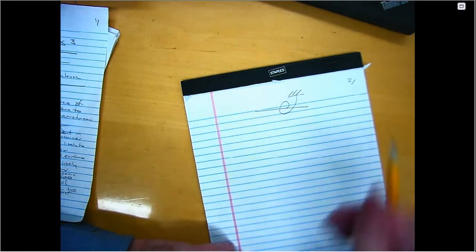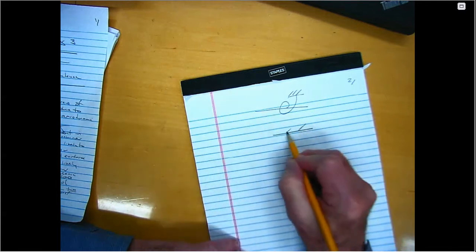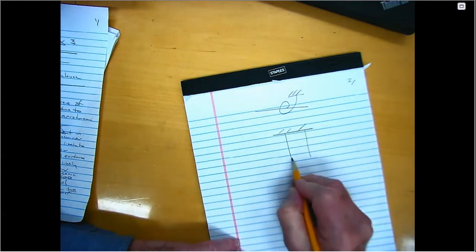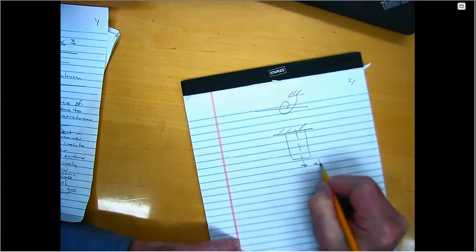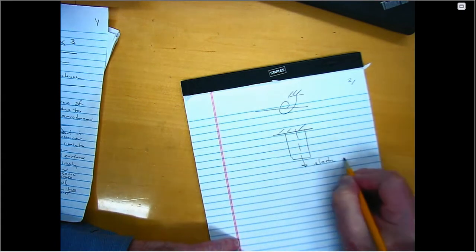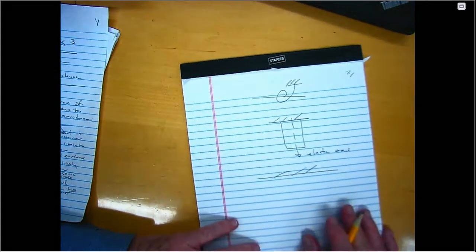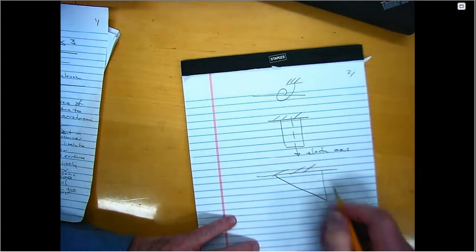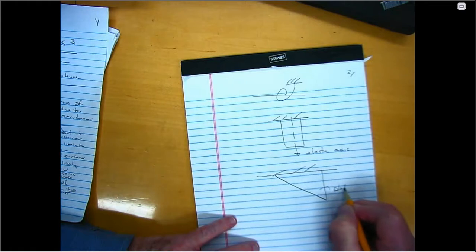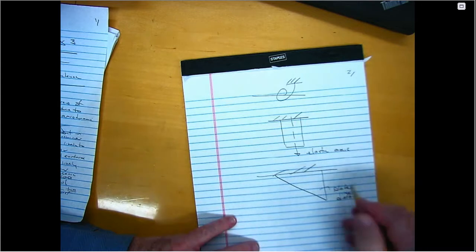Okay, so again, as in static aeroelasticity, we can look at this spring model. We can look at a simple wing model like this, which has a well-defined elastic axis. Or we can look at something that doesn't have an elastic axis, a typical case would be a delta wing. Now this has plate-like deformations, meaning it bends along the chord and it bends along the span.